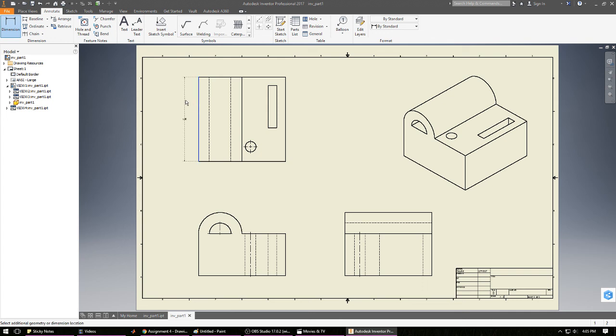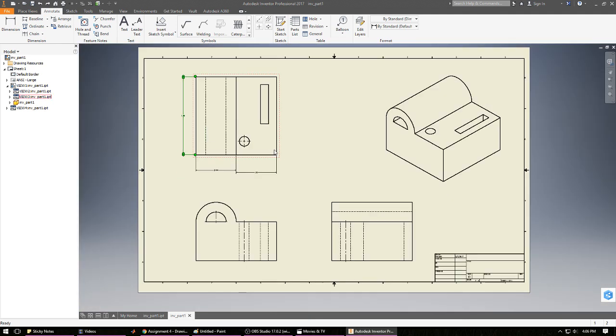You also need to dimension the different sides. Each dimension is its own kind of thing. You can format the text to appear larger. Did you notice how I added this side and it didn't say, oh my gosh, it's over constrained? That's because the purpose of these dimensions is to annotate how big things are broken up between three views. Sometimes, for the sake of making the view easier to understand, you will add redundant dimensions because it is not integral to the construction of the part. So that's something to keep in mind.